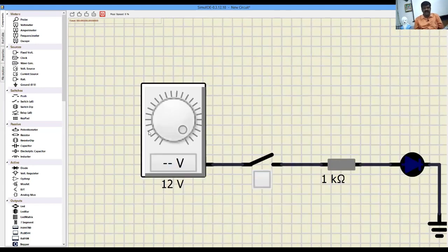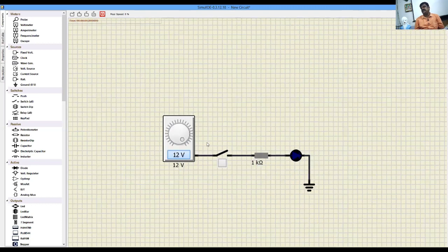Now I am going to explain how to change the voltage. This is the potentiometer. You can change the voltage from 0 volt to 12 volt. Just place it anywhere else and double click and click the column. You will find 3.5 volt. Then you can increase and click, you will get 6.83. Double click the column, then only you will get the output voltage. Increase and just double click, and automatically you will get the voltage source. This is the highest, 12 volt, right? So